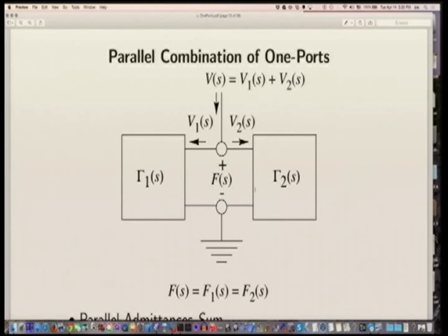All right, so that is the port view. So a port is a driving point or an observation point. Let me just mention that it's not where you put an actuator on one side of a system and an accelerometer on the other side. In other words, if you drive a system at one point and pick up something somewhere else, that's not the same. Your driving point's not the same as your observation point. So we don't normally define a port that way.